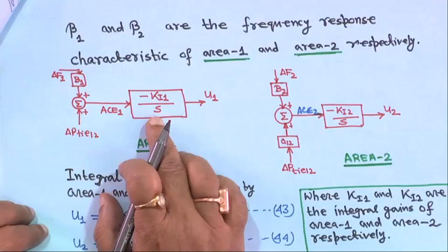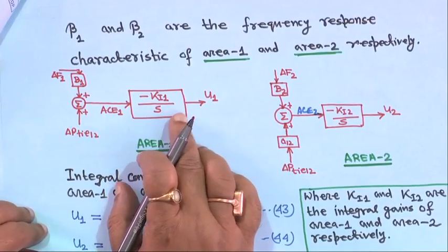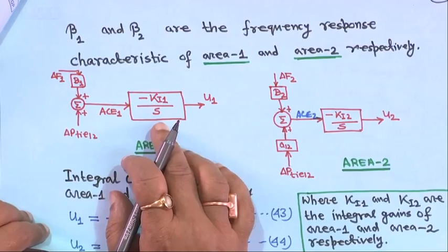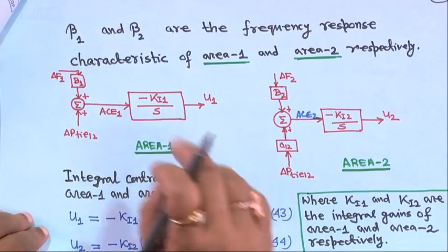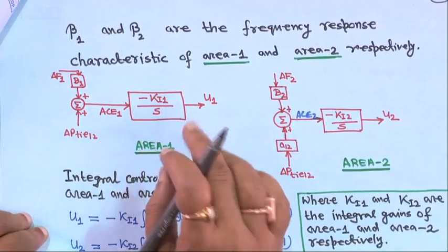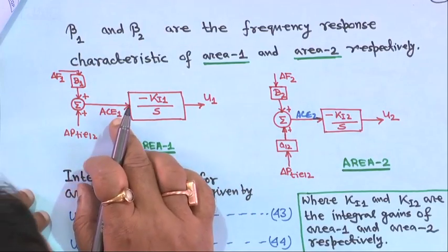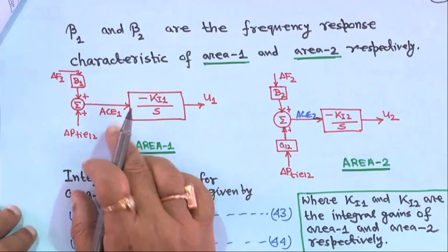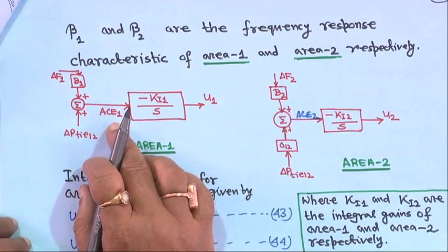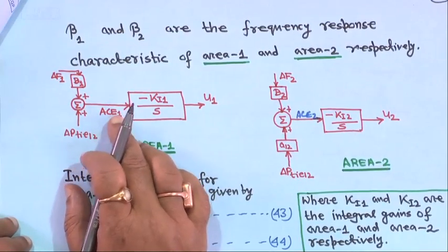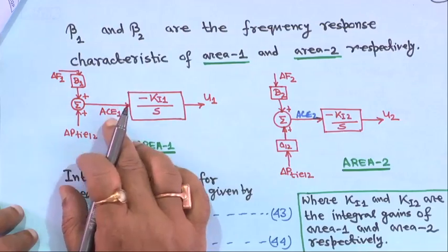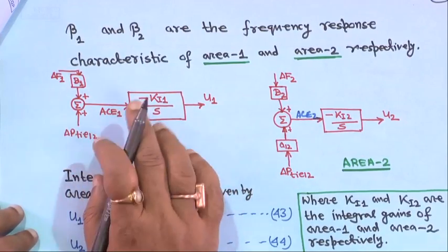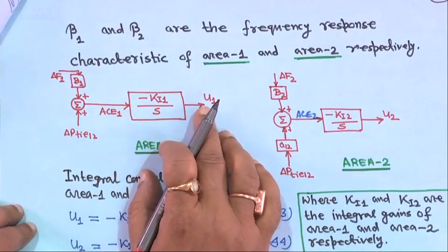Here one can also try proportional integral or PID, but for thermal units PID control is not recommended. Proportional integral is possible. The second thing is that the area control error is not fed to the controller continuously; it has a sampling time, so you have to sample at every sampling instant, for example T equal to 2 seconds, which is not shown here, and accordingly evaluate u.